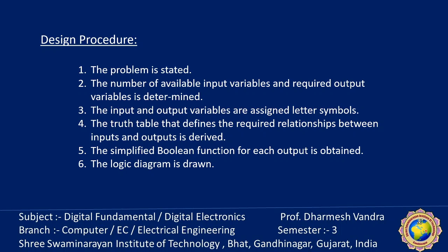There will be a variety of simplified expressions from which to choose. However, in any practical application, certain restrictions, limitations, and criteria will serve as a guide in choosing the particular algebraic expression. A practical design method would have to consider such constraints: first, minimum number of gates, minimum number of inputs to the gates, minimum propagation delay time of the signal through the circuit, minimum number of interconnections, and limitations of the driving capability of each gate.